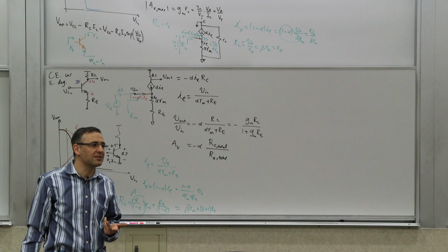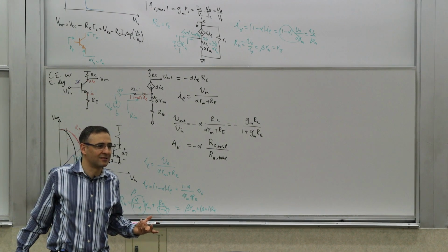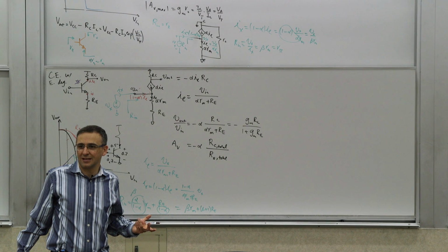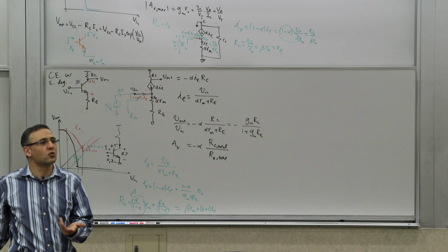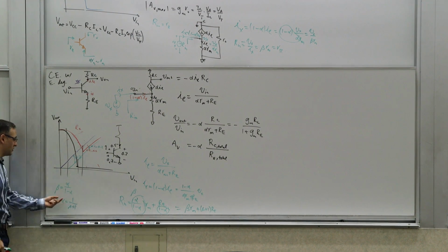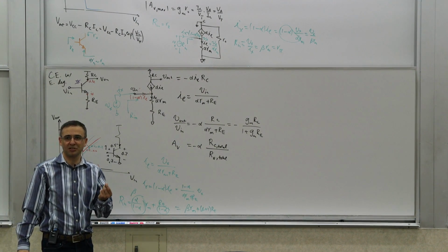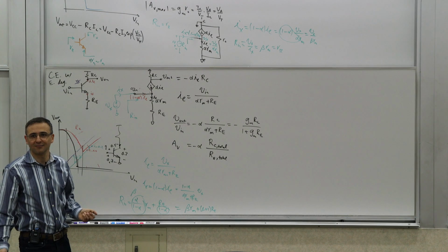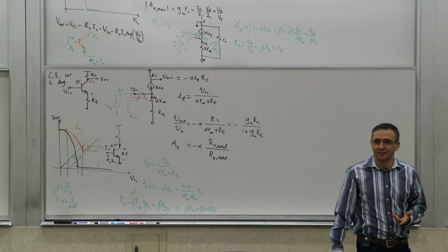Because beta is a parameter that's relatively large and it's very inaccurate, because it has a sensitive dependence on alpha and assumes that alpha is close to 1. So if alpha is close to 1, it's sensitive to it. So this denominator, you literally breathe on it, and it changes. You take a transistor, you measure its beta, and then the number changes. Sometimes you look at it, it changes.